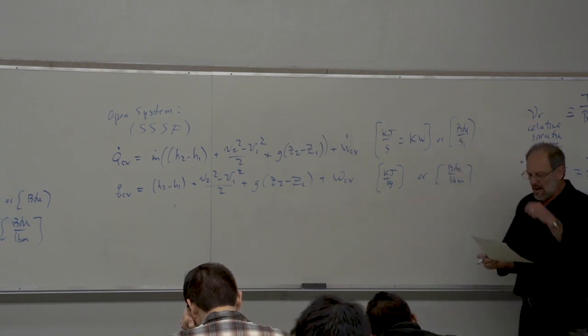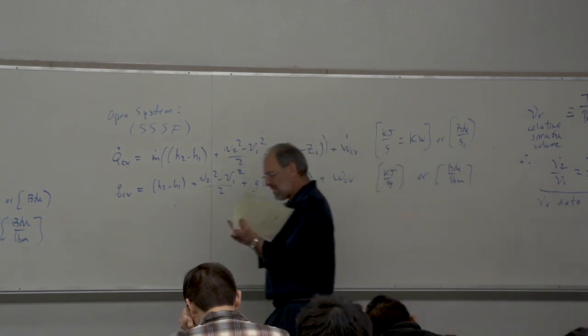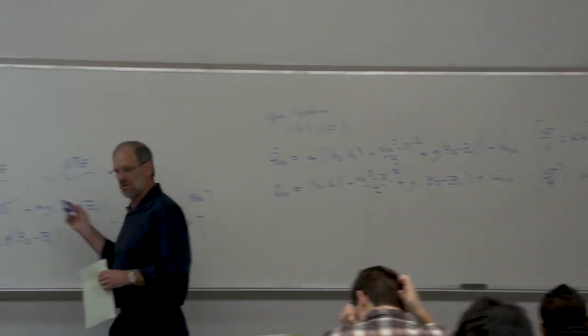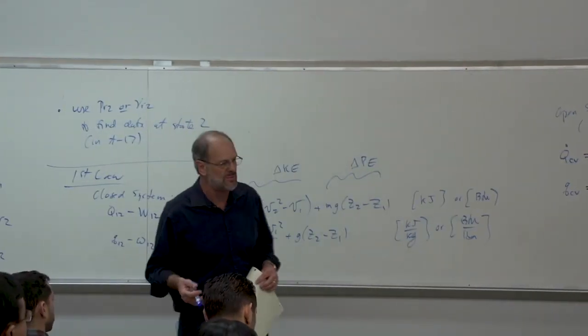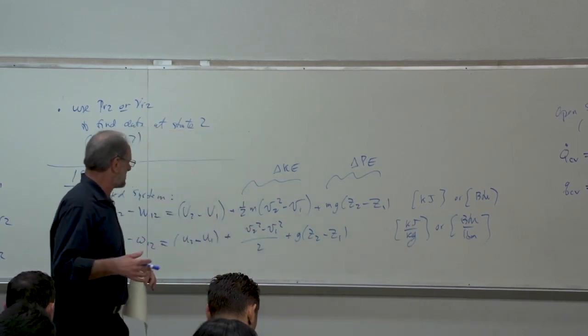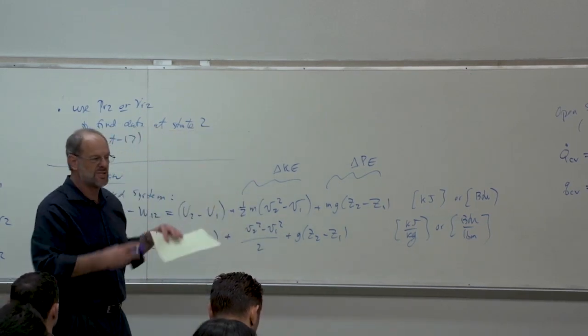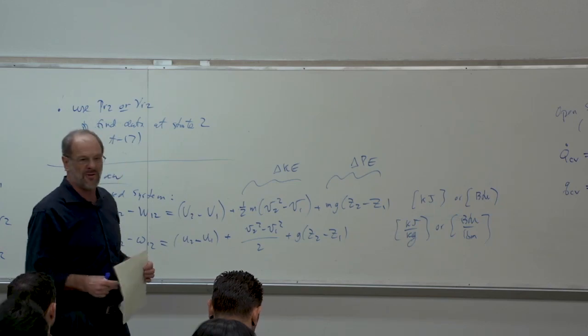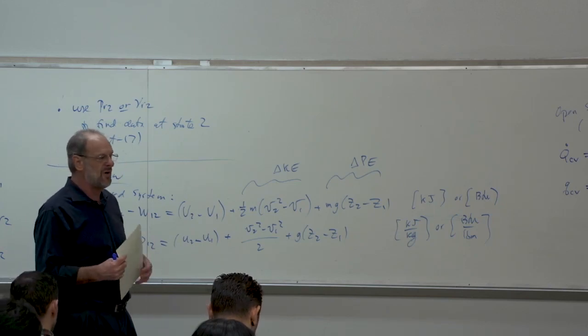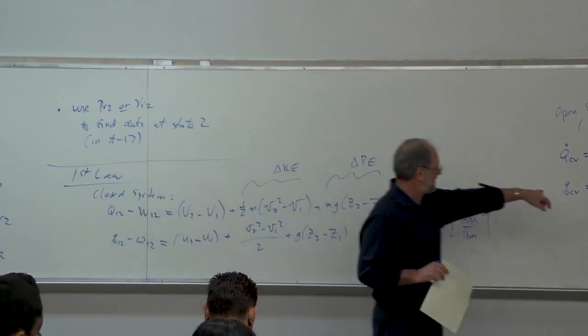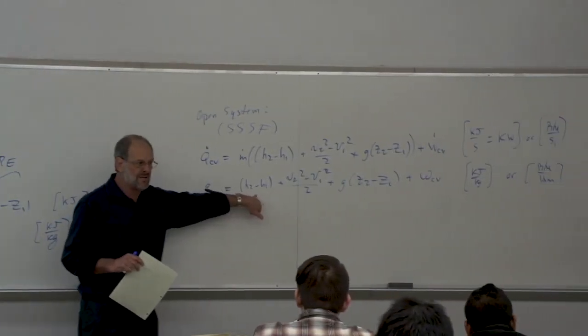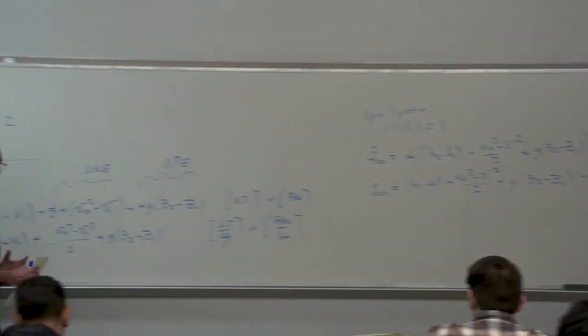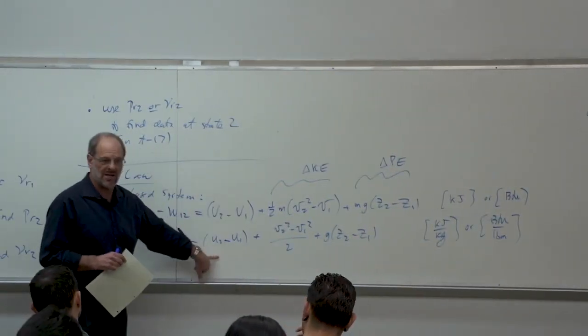Okay. Now, a few things to note. These two equations for the open and closed systems, they sure look very similar, and many students are tempted to just kind of arbitrarily use whichever one they're more comfortable with. But they're different, right? For problems that involve flow, we use the enthalpy, right? For problems that are closed systems, we use the internal energy.